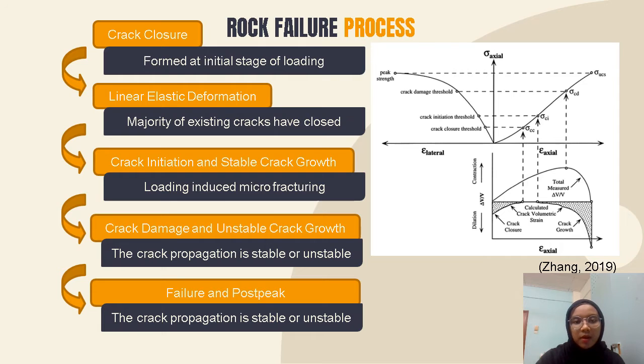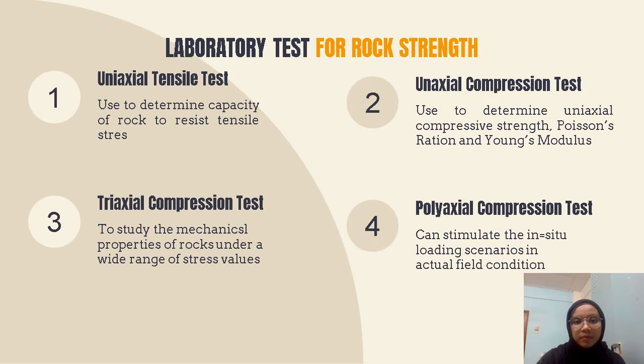When more stress is applied, it will lead to the formation of microfracturing in the rock specimen. The next phase is when the rock specimen is subjected to the highest stress, which might cause damage and also unstable cracks in the rock itself. After the rock has passed the post-peak phase, the rock will start to fail and lose partial or all capacity to bear the applied stress. Hence, there are a few tests that can be utilized to test the strength and the rock behavior.